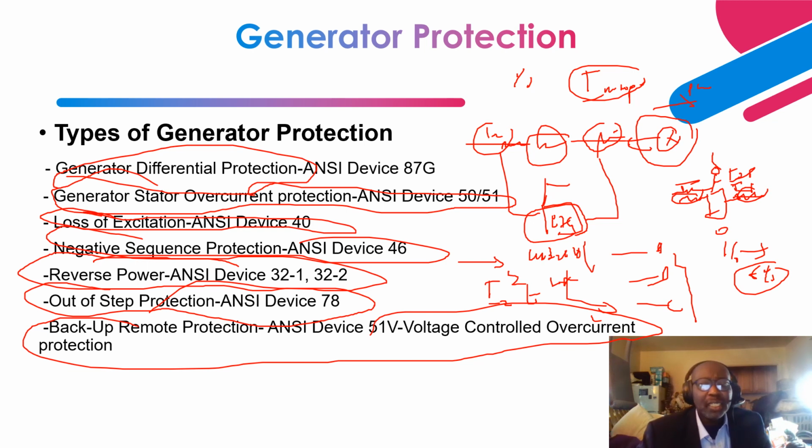Because this fault is so far off, the terminal voltage will dip slightly below the nominal terminal voltage, and sometimes even the current sensed by the differential or overcurrent protection will be very small, quite close to the nominal currents.